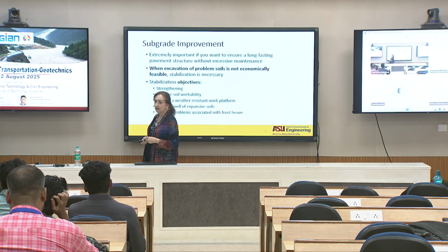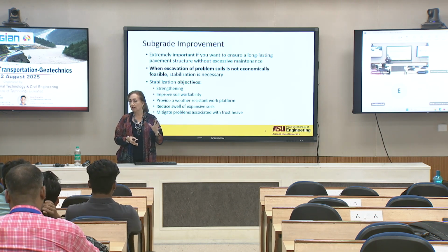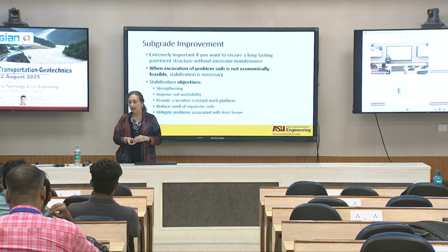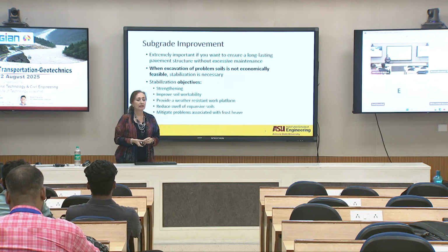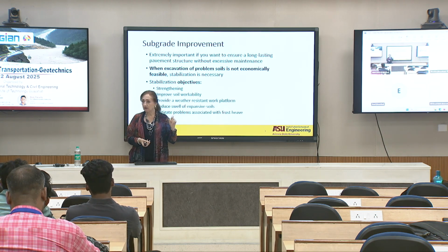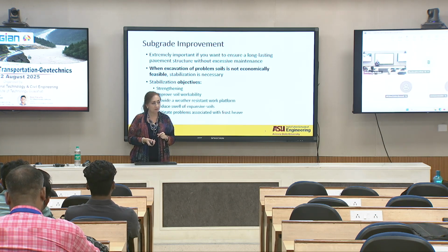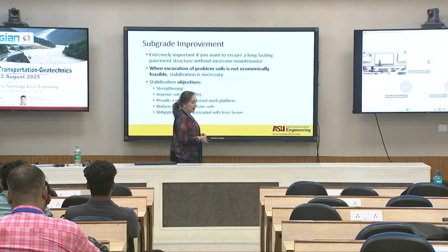One is the strengthening of the soil, so everything has to do with the strength. Another one is soil workability. Sometimes the stabilization has no value in the design of the road, but you need to do it in order to even start working, just to get the loaders and equipment to start compacting the soils.